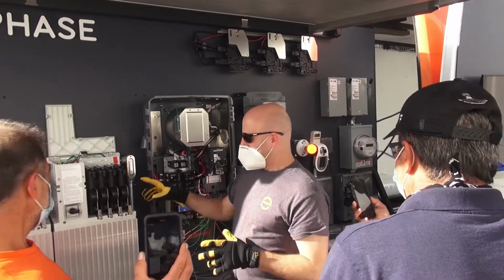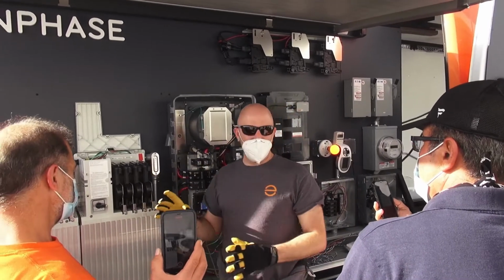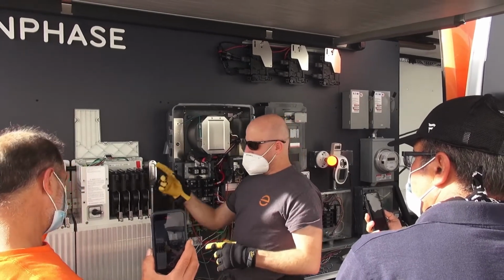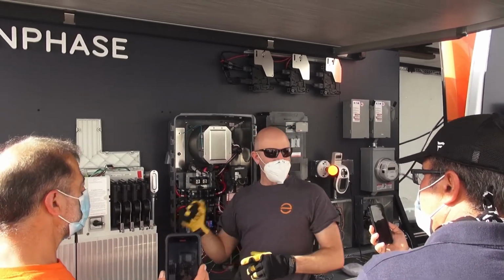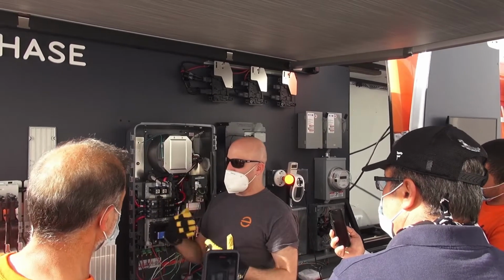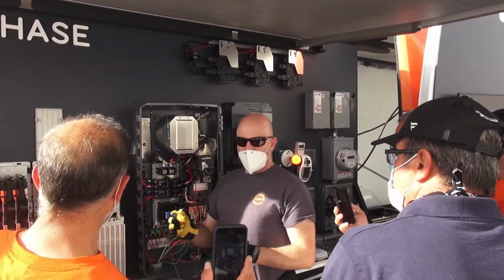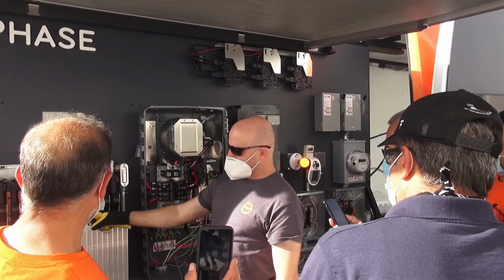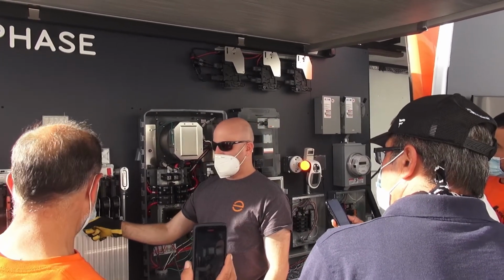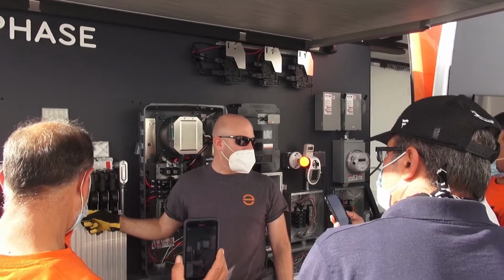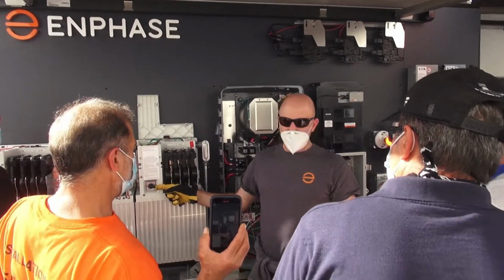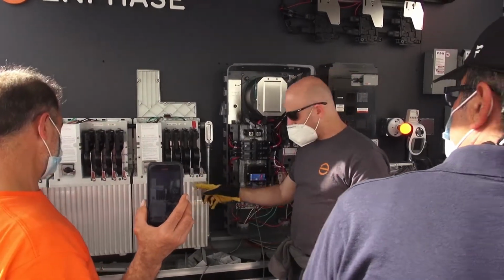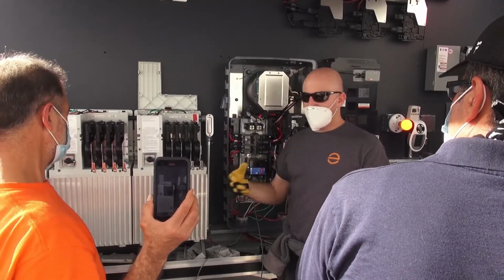If I can't finish commissioning, what that means is I want it in a state where the batteries can charge or discharge. That's a system that's fully operational. If I have to leave that site before that's the case, you must turn off this DC battery disconnect switch. Okay? If we're not finished, if the system's not up and running where it can charge and discharge and operate fully.